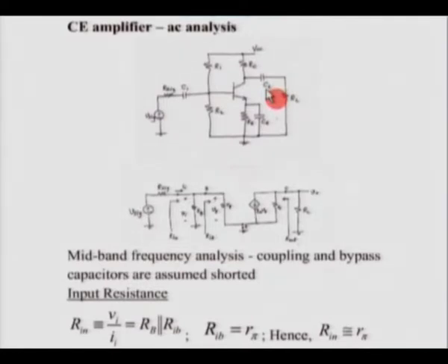Once again, how do I decide the polarity of C2? Here again the same principle: we need to look at the side we are sure about the polarity. We know that the collector side of the capacitor has a higher positive voltage, whereas the load side is connected to ground. So, we would choose a positive polarity on the collector side and a negative polarity of the electrolytic capacitor on the load side. Once again, typically the value of C2 would be about 10 microfarad.